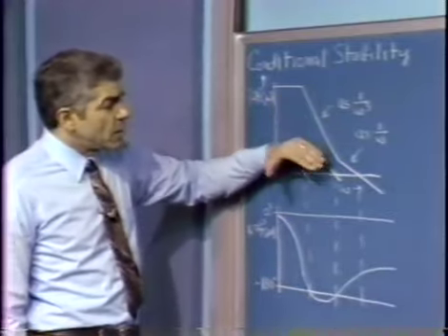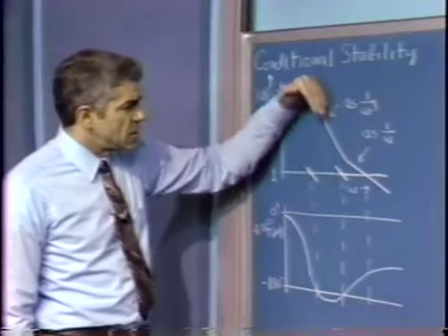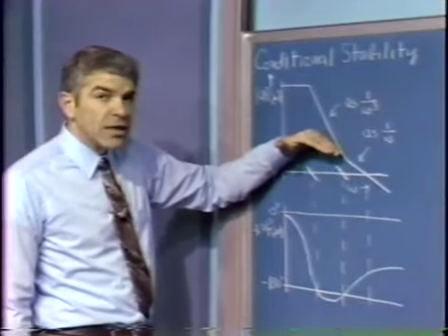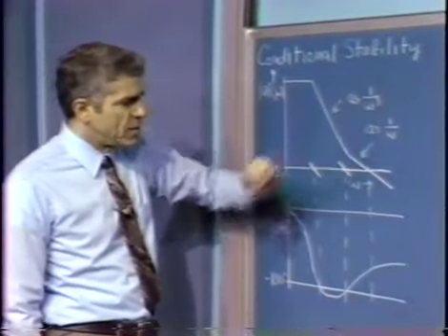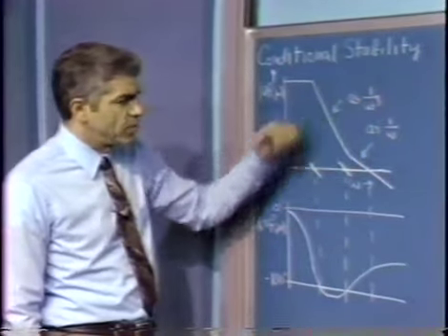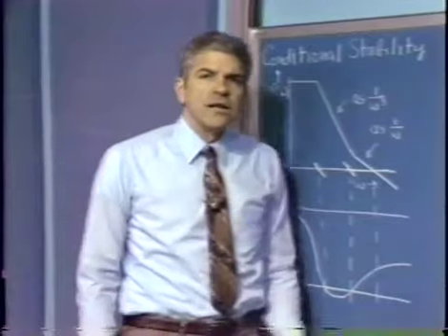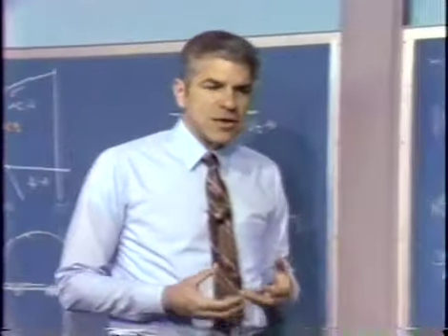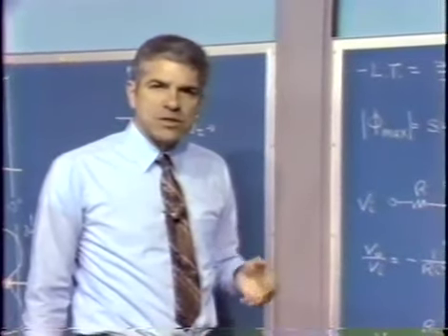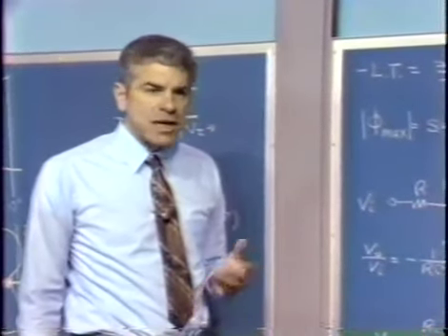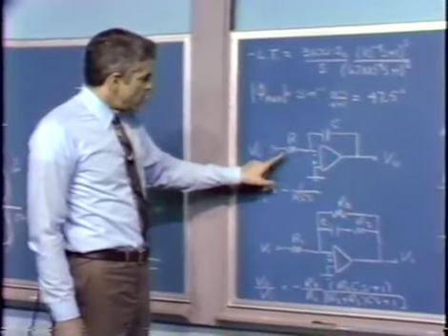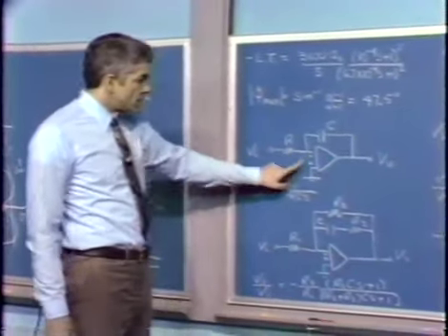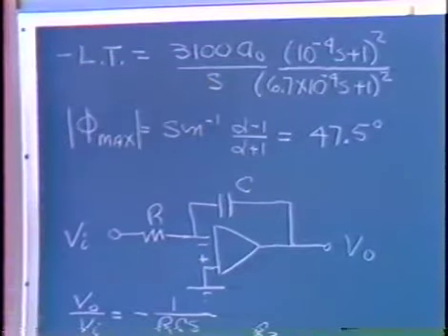We might want to extend that. We might want to get even greater desensitivity than we could get with even the two-pole roll-off, and so we might go to a higher order roll-off, a three-pole roll-off, again in an attempt to improve desensitivity. So while the demonstration system we're building up is a made-up system, if you will, this sort of situation exists in many actual systems. Well, the building blocks we're going to use are an integrator so that we can get the pole at the origin.